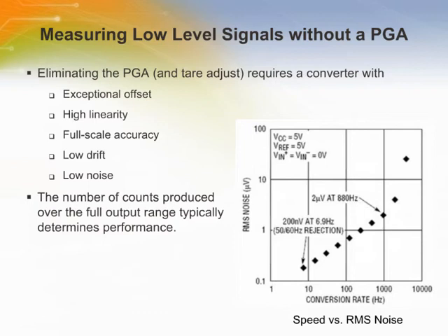Programmable gain amplifiers are commonly used in systems where a small input voltage needs to be applied to a wide input range analog to digital converter. The convention is to amplify the sensor output voltage range so that it matches the analog to digital converter input range. However, the system performance is dominated by the noise performance of the programmable gain amplifier as well as its offset, full scale, and linearity performance. Programmable gain amplifiers degrade system performance by introducing added error sources, drift, cost, and complexity.